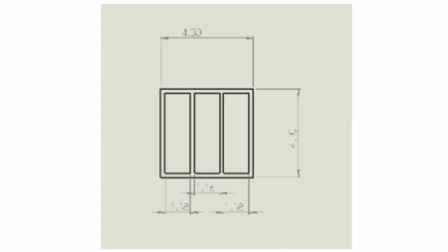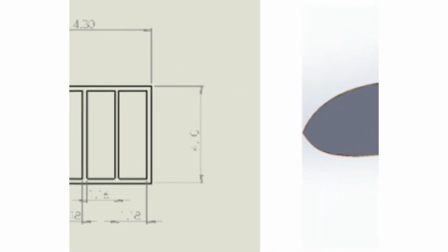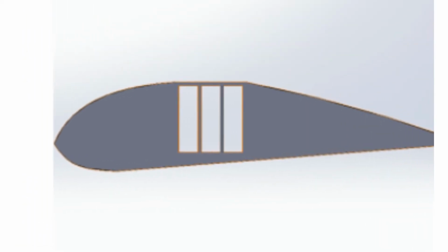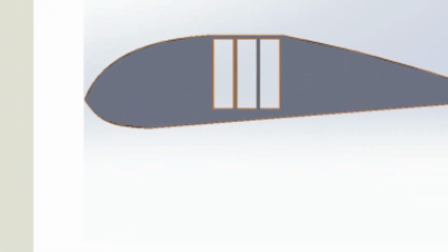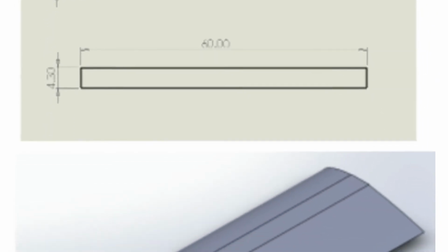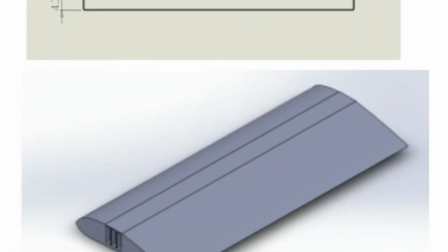In SolidWorks, we deduced that the cross-section of the spar in a double I-shape demonstrated improved stiffness and bore a greater load of force before it would fracture compared to the other shapes that were tested. These included a single I-shape and a normal basic rectangular beam. Double I-beams distribute the weight evenly, and they also prevent higher levels of tension from proceeding through the web. As well as this, they have a larger moment of inertia, which counters buckling.